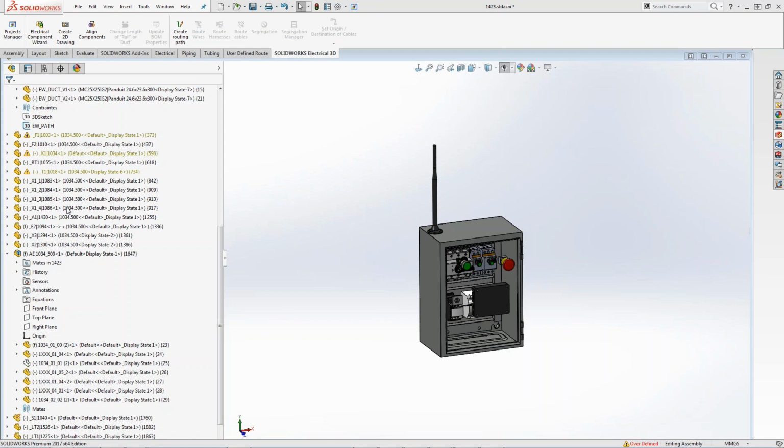I got more feedback. I got an interesting one here. I have 100 different cables, and how do I have 3D routing of them partially? For example, I need a few power cables. If I connect my wires in 3D, everything will be connected automatically, and it's always trying to look for the shortest path available. But what happens if I have to separate, let's say, power and control wires?